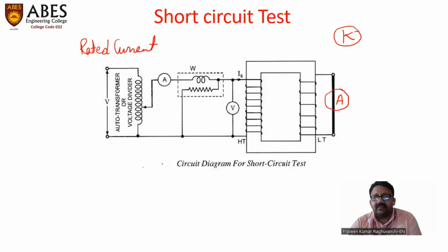The reason behind the high secondary current is that in the secondary winding there is no load impedance, and due to the short circuit, a small voltage appearing across the secondary winding is capable of developing a considerable amount of current. In other words, under short circuit condition, with the application of a very small voltage, there is a rapid increase in winding currents.